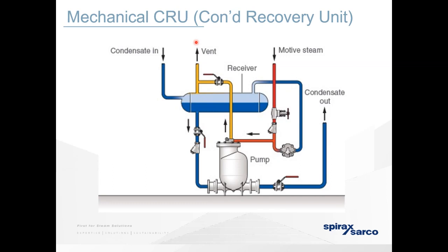So if you're talking about trap sizing, there's not really a need for calculation on those. The idea is that when a system is cold, we treat it as if 100% of the steam is being turned into condensate. This is before warm up. So when you size steam traps, you would size them for double the load. If you have a running load of 500 kilograms, we would say size the trap for 1,000 kilograms, because that allows ample space for runoff when draining the system to try and get it warm quicker. I'm hoping that answers that question.